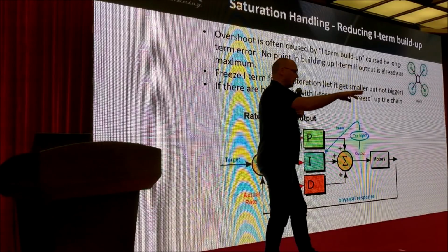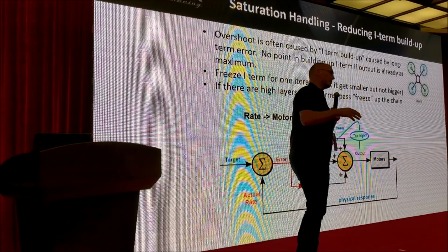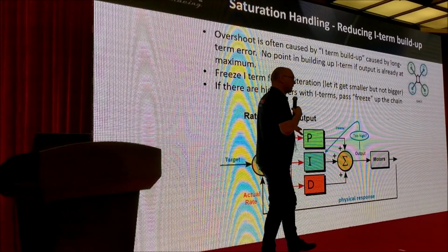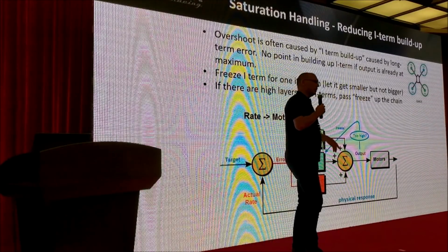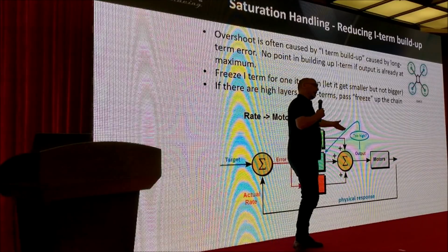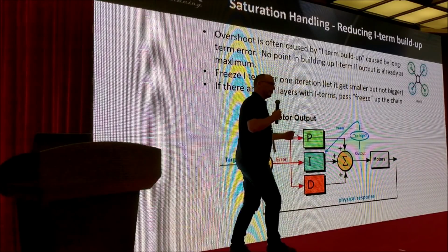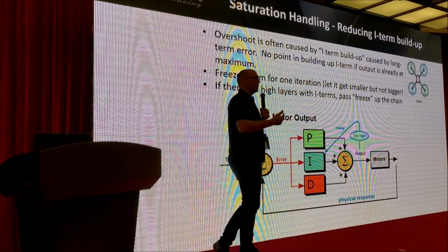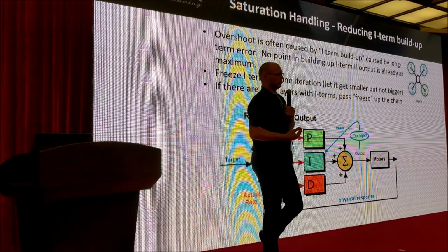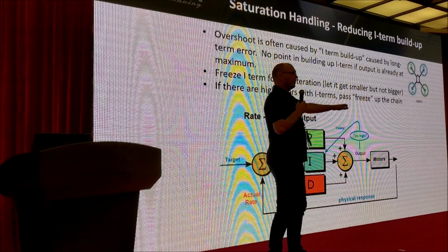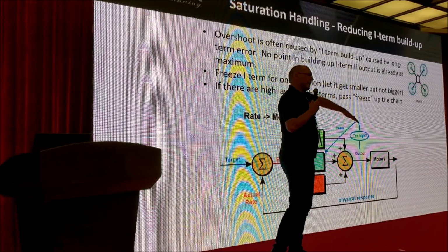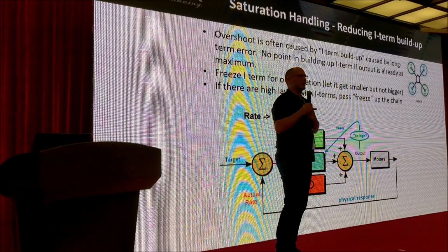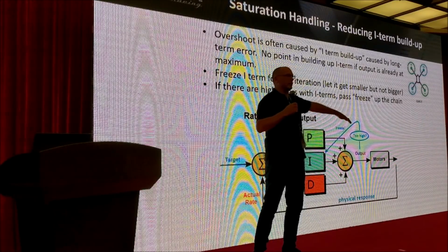And so for you guys, when you're looking at our PID controllers and looking to implement your own version of these with a different type of controller, it's very important that you handle those saturation events so that the controllers above know when they're not going to get what they ask for. So when I want this angle and I can't have it, I need to know so I don't make silly decisions thinking that I will get that angle.